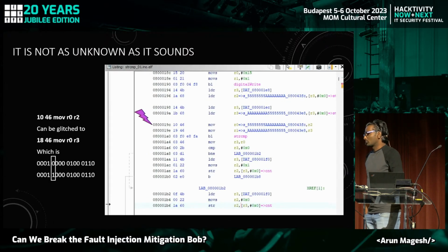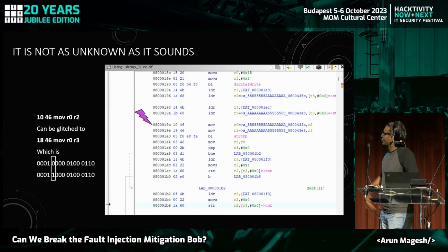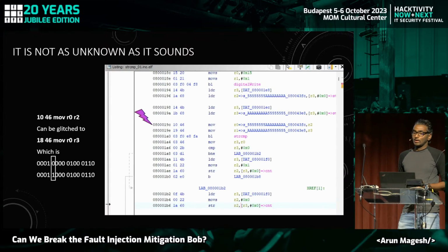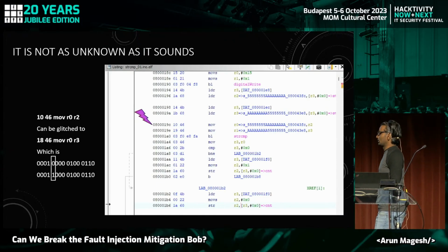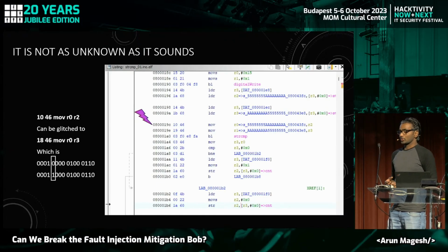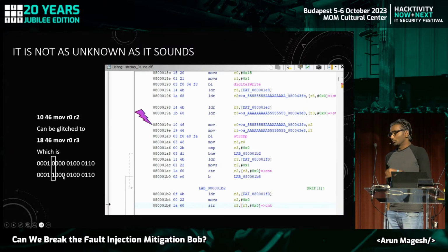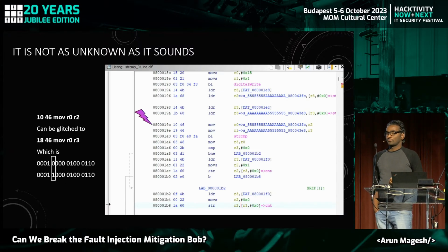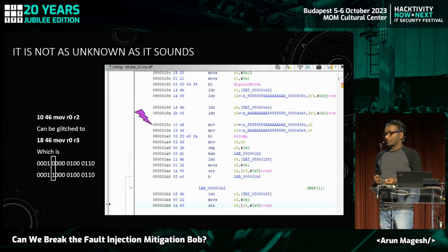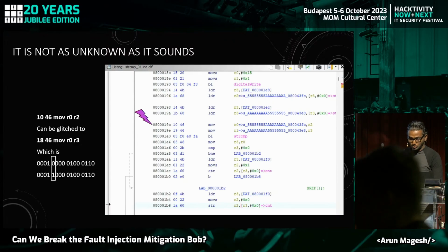This is basically called fault modeling. Again, I'm just using one glitch as a model. There are still more models you can use, 2-bit flips, 3-bit flips. The reason why I went for 1-bit flip is there are very low chances for it to control, for example, 2 different glitches. For example, if I want to set the first one to 1 and then this one to 1, it's very hard to glitch it because even if you have a controllable glitch, it's very hard to set these 2 random values. But to flip a single one, there are high chances that you can tamper with them.